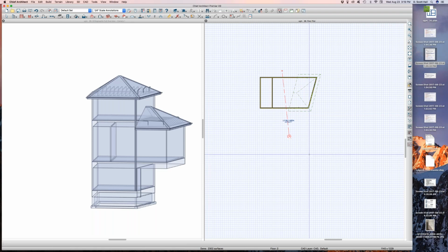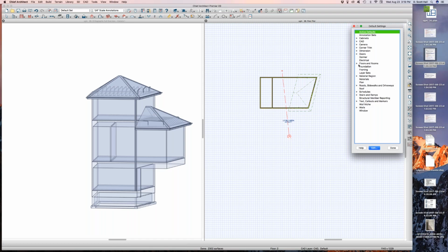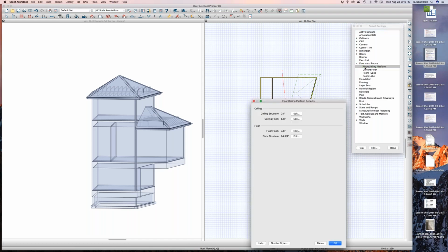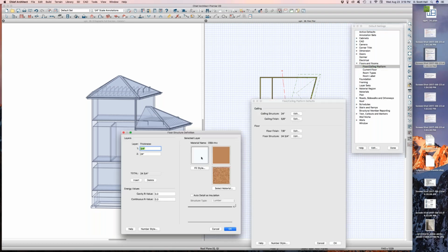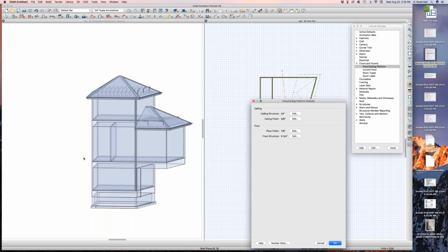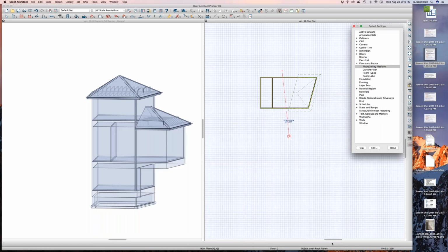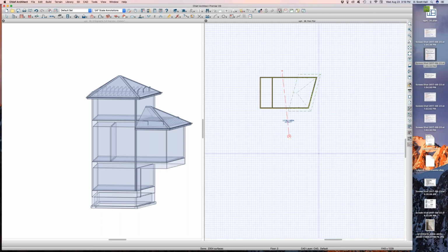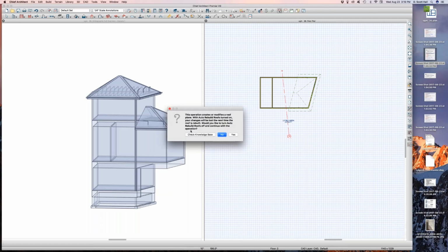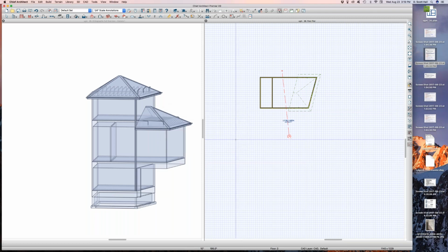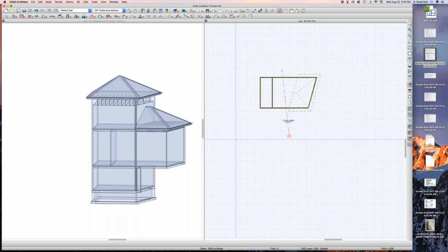Okay, well, watch this. Just so we all are on the same page on this. Floor ceiling. I'm going to change the floor platform to 6 inches. The question is, do you think the roof's going to move? Oh yes, it will, because it's on automatic. Automatic rebuild roofs. God, hit it. No, it didn't, because I don't have automatic roofs on anymore.